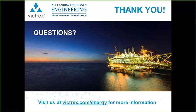Alexandra, do you have anything to add to that one? No, I completely agree with you. And even if you're not melting, if you're processing, I think you will get different mechanical properties, and life estimation based on those mechanical properties may change because of the processing, the crystallinity, and these kinds of things. So processing is definitely something to be looking out for when you're reading these results, so that you make sure that you're testing the right stuff according to what you need to use.